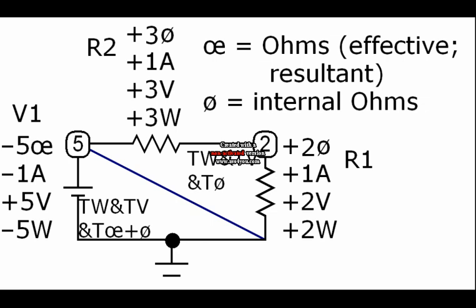By implication, you're also saying that its effective operating resistance is going to be a negative resistance whose value is undetermined until you hook it up to a bunch of positive resistances. So in this situation it has -5 effective ohms.